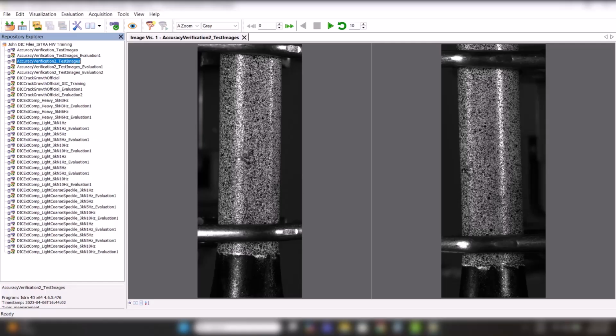The calibration process is the same. The calibration parameters, masks, start points, rung steps, smoothing procedures, and evaluation strategies are all fundamentally approached the same way. The focusing process is also very similar, although there is one important difference that we'll talk about in a moment. In my experience, there are really only two practical differences when performing stereo DIC on planar versus non-planar specimens.